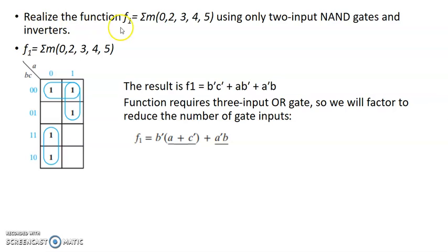Now we'll discuss an example on gate fanning. Suppose the minterms are given, and we must realize the function using only 2 input NAND gates and inverters. First simplify this using a K-map. In this example we have written the K-map in a different way, with the most significant and least significant variables marked. The cell values are 0, 1, 3, 2, 4, 5, 7, 6.